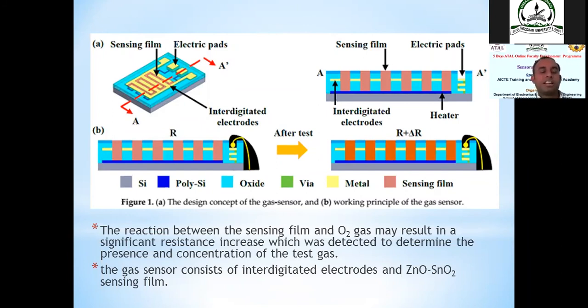So there is a possibility that we can design new structures, and based on the structures, the sensing time also can be changed. If we change the material, its selectivity will change. The fabrication type also matters: in which process it is done, whether PECVD, normal CVD or any other deposition process, based on that also its properties will change. And the design or mass of those metal oxide semiconductors will decide how much heating power is required, and obviously the heater structure also will decide how much power is required and how fast these devices will work.